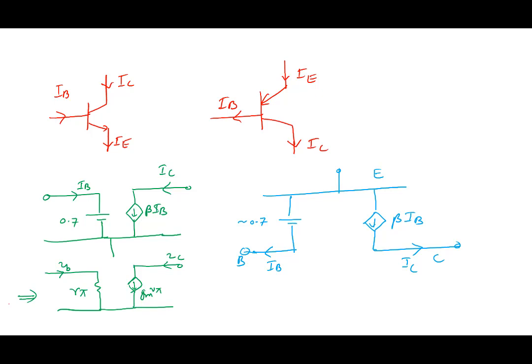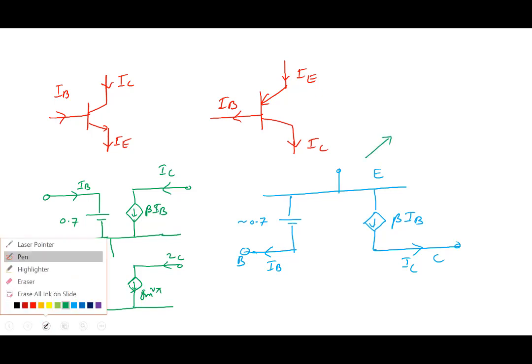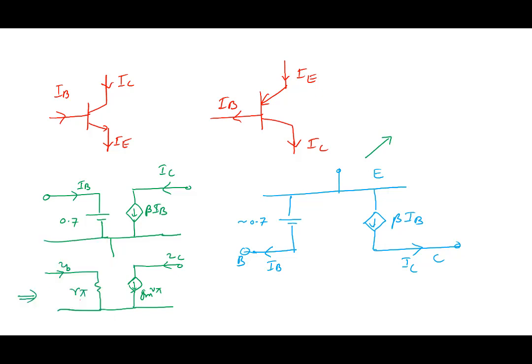If I were to draw a small signal here, what will it become? Well, there is an emitter terminal, here was the emitter, right. So there's an emitter here, there's a base here, between base and emitter again there is an R pi. The base current flows like this, IB, as you can see here, just the analogy.